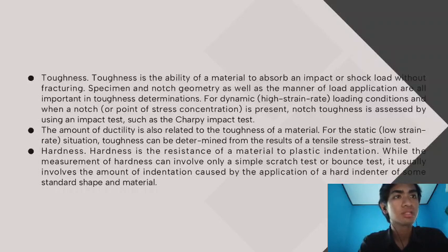The amount of ductility is also related to the toughness of a material. For the static situation, toughness can be determined from the results of a tensile stress test. It is related to the area under the stress-strain curve up to the point of fracture. The ductile material can accommodate greater amounts of strain than brittle material.